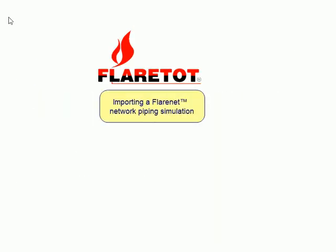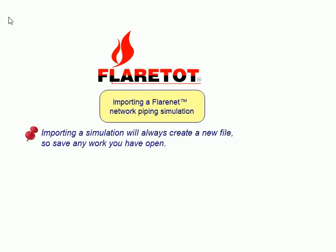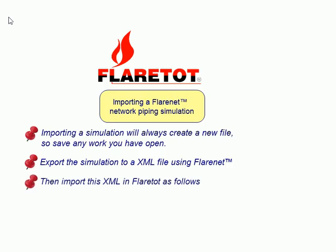First, we show you how to import a Flarenet simulation. Note that importing a simulation will always create a new file, so save any work you have open. You need to export the simulation to an XML file using Flarenet. Then, this XML file can be imported into Flaretot as follows.